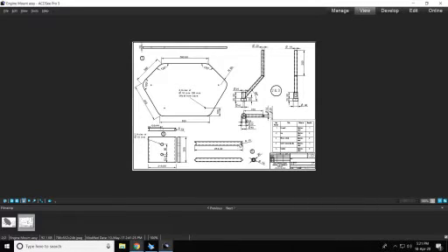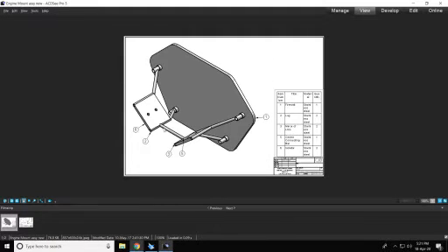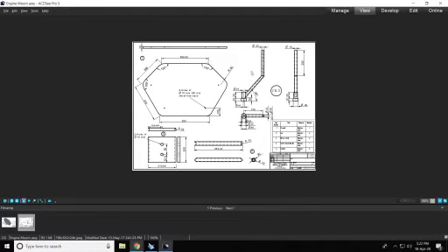If you make any mistakes in dimensioning, you won't be able to assemble it because the relations will conflict. Meaning, let us say the connecting rod is 254.42, but you somehow made an error and designed only for 200. That 54 mm you can't compensate anywhere, so that will come as a gap here. So while creating parts, strictly stick to the dimensions given. In spite of that, sometimes errors happen. Even I faced an error last time. Then we can see what alterations can be done.